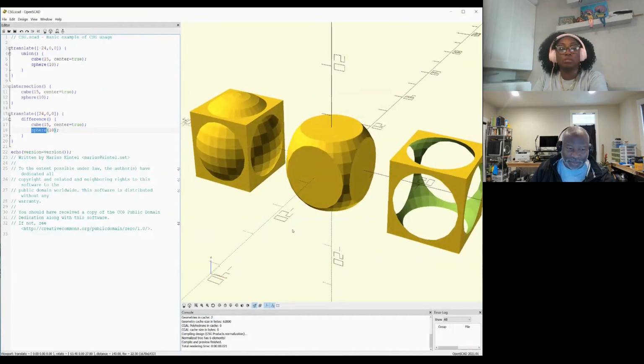And then this turns into all sorts of things. This one that I'm showing here can be completely done in code like that, with just more complex things. So take the cylinders and union that with a rectangle, and then you end up with something that looks like this pencil holder. All right. So this is called constructive solid geometry. This particular tool is called OpenSCAD, and it does exactly that. A lot of people will look at that and go, "No, thank you. That's too complex for me."